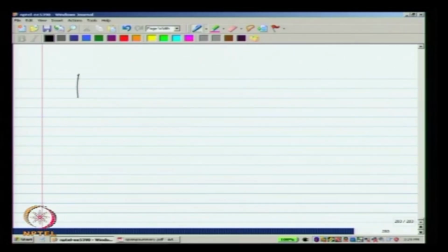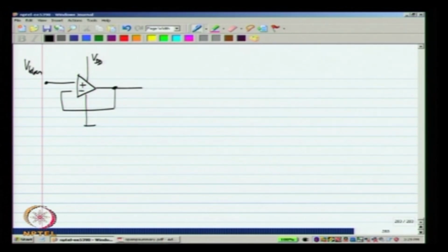Before we go further, a quick clarification on how we connect the load to the two stage op amp. As I mentioned earlier, we are operating with single supplies. So, the input signal and the load must be connected to some bias voltages. We have VDD on top and the ground on the bottom. So, the input will be some V bias plus Vi.